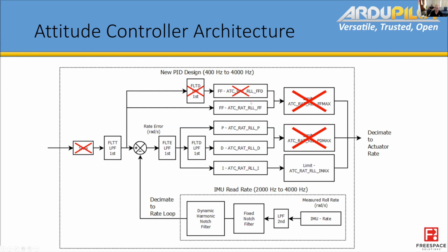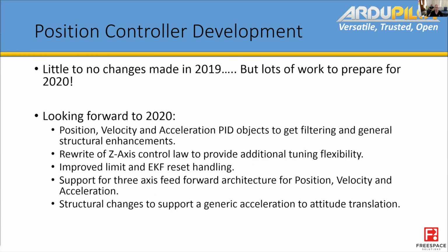The feed forward is really simple in that you look at how much output is required to move at a given rate, and then you can calculate the feed forward term straight from that. In an auto tune case, that's a little bit more complicated because we can't just sit there doing rolls, but the principle is there. The beauty of auto tune is we can take very precise measurements in short times and take multiple of them to average out a nice approximation of the ideal value.